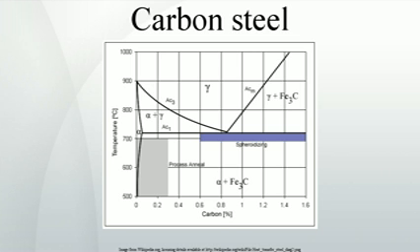Process annealing, a process used to relieve stress in a cold-worked carbon steel with less than 0.3 wt%C. The steel is usually heated up to 550 to 650 degC for 1 hour, but sometimes temperatures as high as 700 degC. The image rightward shows the area where process annealing occurs.